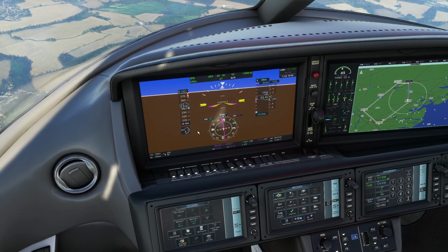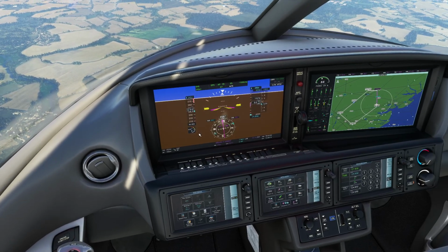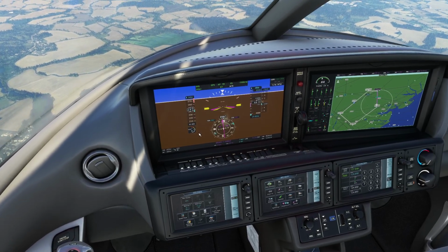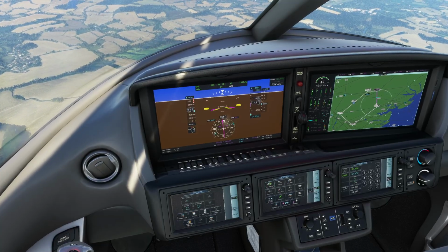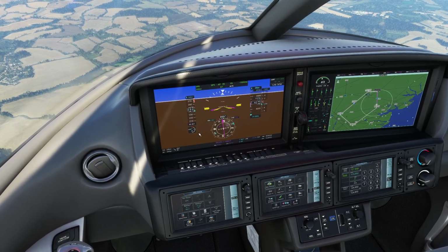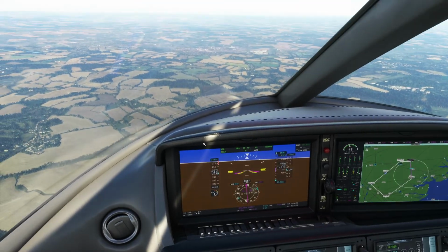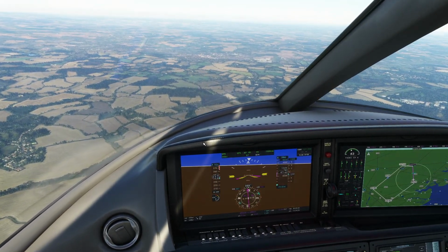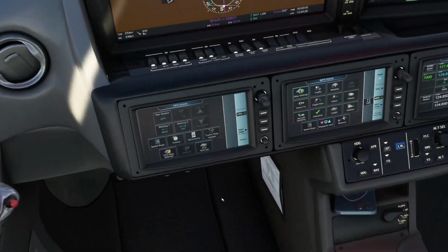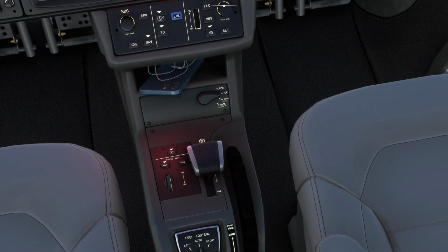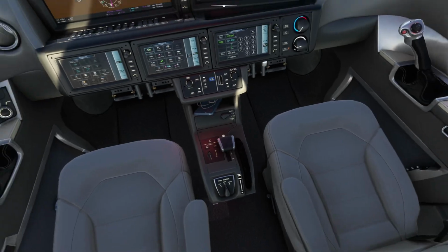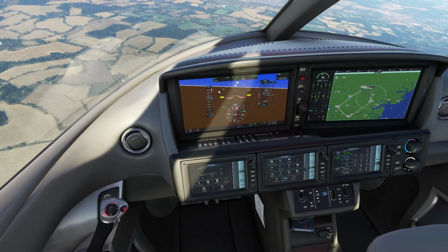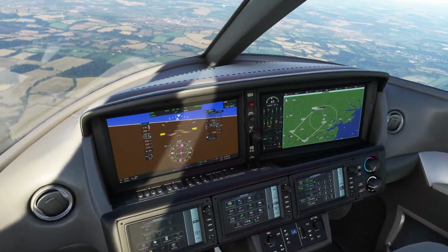So you really do need to keep an eye on it when you're doing this kind of thing, and use the air brakes to help if you need to. Or spoilers, flaps, whatever you've got. It depends what speed realm you're within. So you will remember looking at the flaps, they have a maximum speed, so you can't use 50% flaps until 190 knots. We're doing 240, so we can't drop them yet.